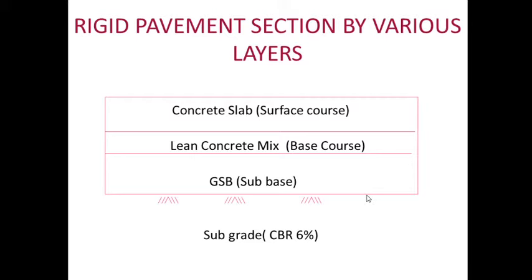The various layers of the rigid pavement are subbase, base course and surface course, and the bottommost layer of the pavement is called subgrade. The subgrade is compacted natural earth immediately below the pavement layers. The top of the subgrade is also known as formation level. Over the formation may be subbase, base course, and surface course.